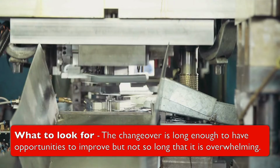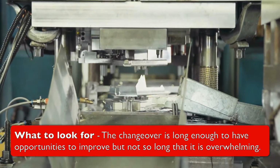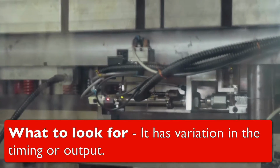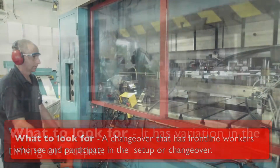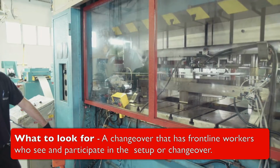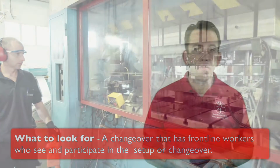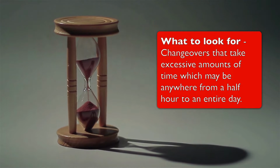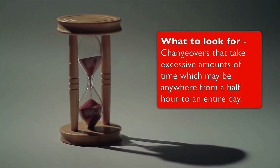The changeover is long enough to have opportunities to improve, but not so long that it is overwhelming. It has variation in the timing or output. You can also look for a changeover that has frontline workers who regularly see or are part of the setup or changeover. This will be critical in your resources in reducing your times. These people can be talked to and provide valuable information. Other opportunities are changeovers that take excessive amounts of time, which may be anywhere from a half an hour to an entire day.